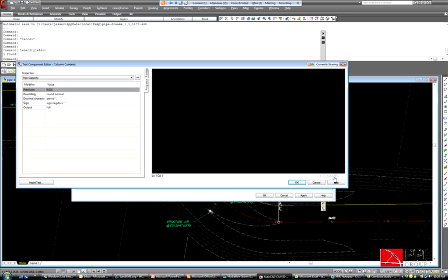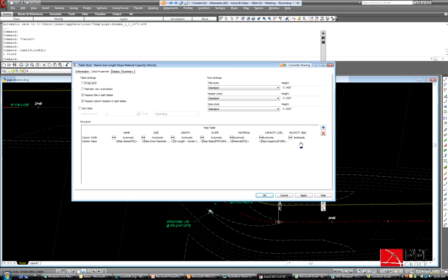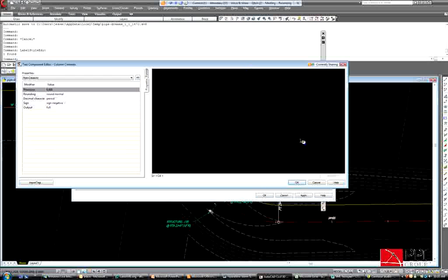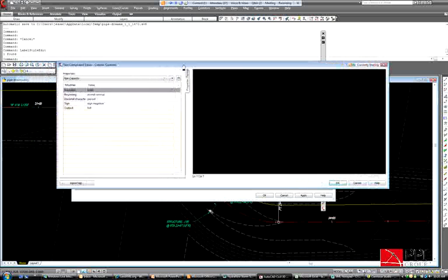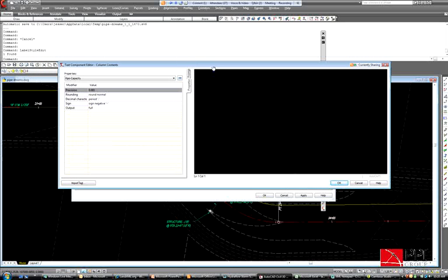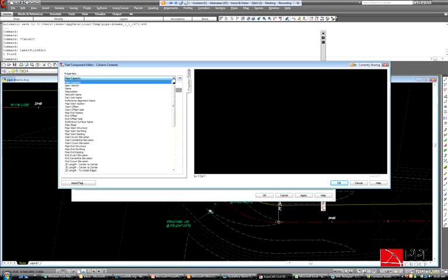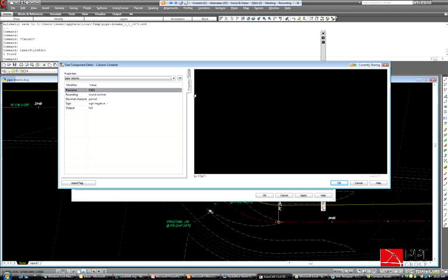So you can see, I'll back out of that for a second, but double click on any of these to affect what's going on here. I'm going to come down into this first row of this velocity column, double click in there, and that brings me into this label editing format that you're used to if you've edited any of these label styles. In here you can see my pipe capacity is there, my pipe velocity is there. Again, because I've written an expression, it shows up in these properties for these specific label and table styles.